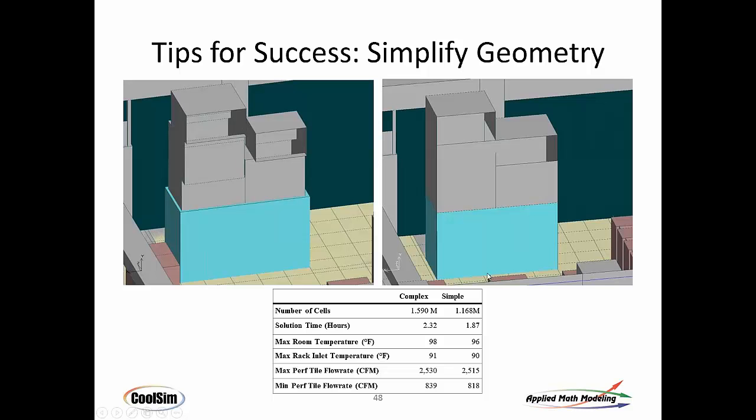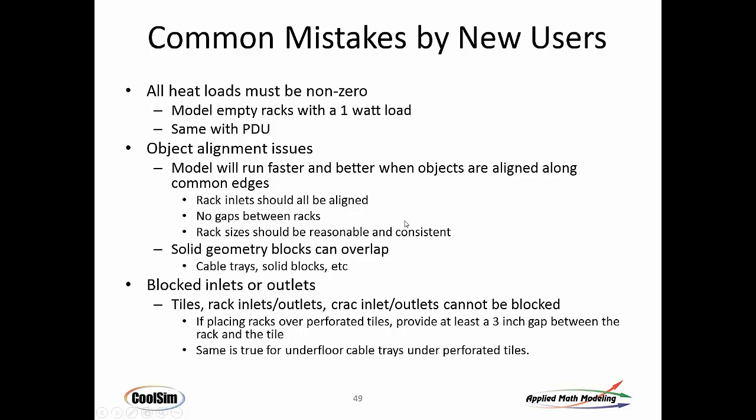The cell count's going to drop. You can see here that the cell count dropped by 400,000 cells. Solution time dropped significantly, more than 40 minutes. Temperatures didn't really change very much at all as a result of that. So try to keep it simple.